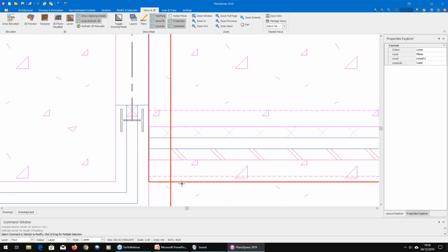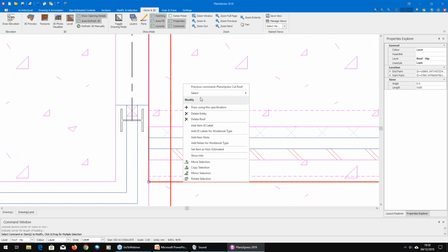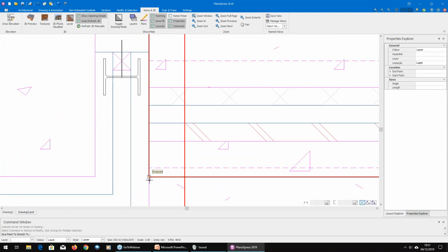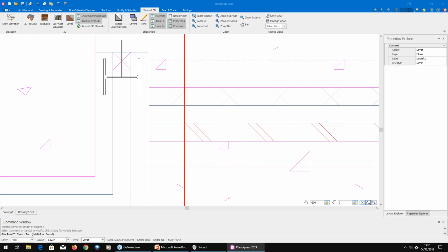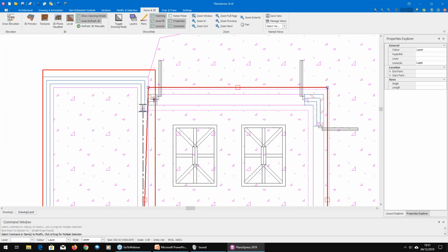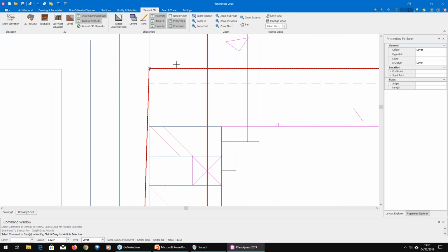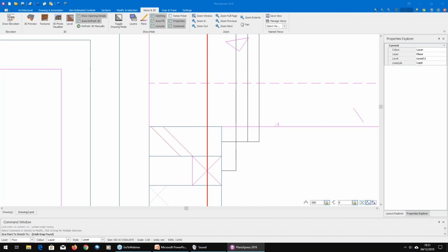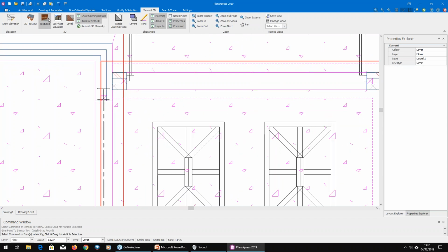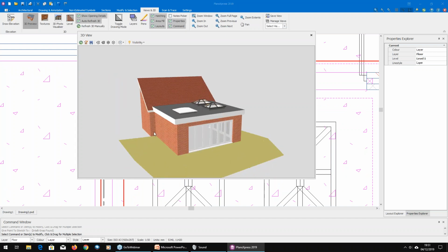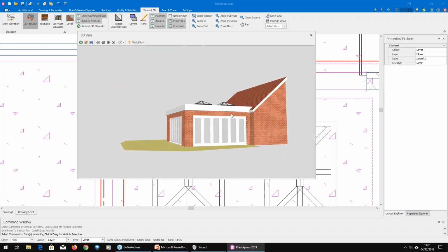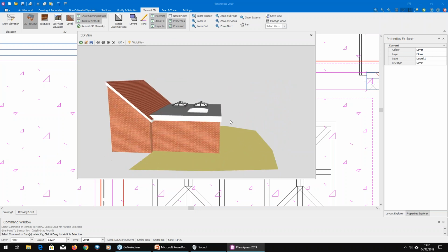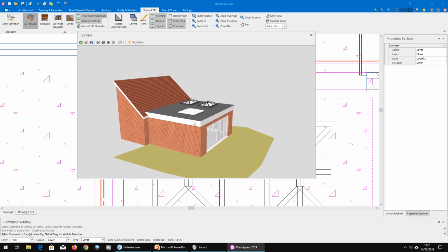It wouldn't look so bad actually if I took this flat roof and brought it in a little bit. So I go, select all lines for this roof. Let's go with that 200. That's a trick as well. If you've got any kind of roof line selected, or actually any line whatsoever, as long as you've got the blue box, if you left click on it once, instead of moving it around, you can use your arrow key to tell it to go in a direction by a set distance. Makes moving lines like that much nicer. There we go. It's practically a work of art now.